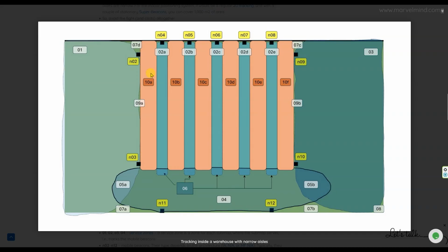These two station beacons are taken in 2D, and you can see they can cover a huge area, for example, 25 by 25 meters. So the maximum distance would be less than 30 meters recommended. Some cases could be more, but we don't recommend overstretching the capabilities. But this area, what we are discussing, is very narrow, with multiple small submaps. Of course, there will be handover zones.